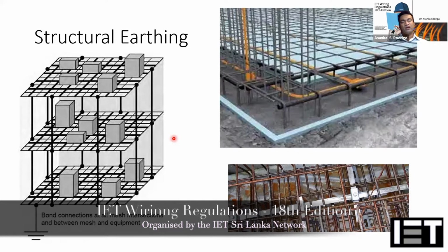If the main protective device protects at the most extreme end of the distribution system, then that is also sufficient. But keep in mind, in that case, if an earth fault happens at that point, the entire building or entire installation will be disturbed. So it's up to the designer to decide what level to put these RCDs. But overcurrent protection is mandatory at every origin point.